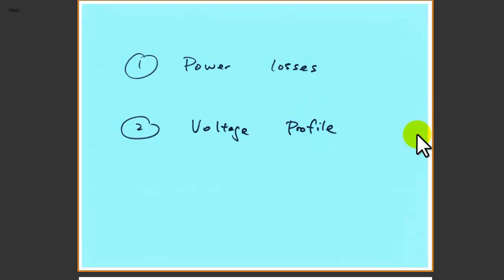And finally, the major objective of this course is to determine, after having all this detailed modeling, how much the power losses would be, because in the transmission system we sort of ignore the R, the resistance, because the reactance is much larger than the R. It's not the case in the distribution system. And then there is also voltage regulation within a feeder. Knowing the voltage profile is very important in distribution engineering. So with that, I think this will conclude lecture 2.